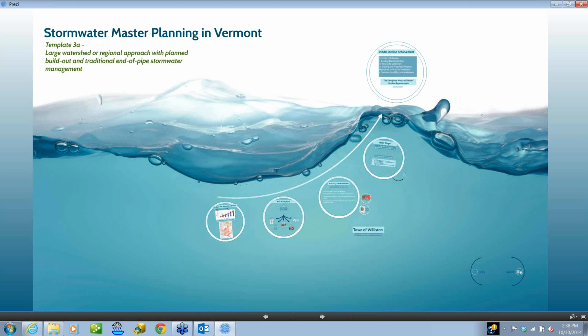And so using a tool that's just going to be predicting where the highest flows are could guide you towards likely problem areas, if you're using the model as a tool to boil down where the highest flow areas would be. I think something like a TR20, TR55 would be a good tool. I wouldn't typically use a model such as WinSLAMM, the source loading and management model, which is geared much more towards the urban environment. It's not really going to be applicable in that type of environment. So I would think something like just a runoff model would be most useful in a typical rural road Vermont environment.